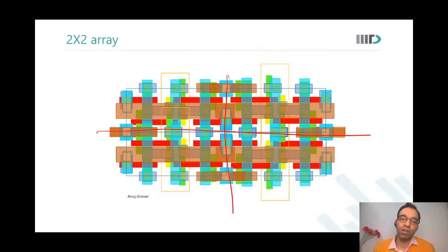If I would not mirror along this axis, then there will be a disconnect. I wanted to connect a bit line on the Passgate, and I need the bit line on this side. If I just translate it up there, there would be ground from this side and bit line from this side, and they would not merge. Therefore, mirroring on this side is also required. Yes. Okay.